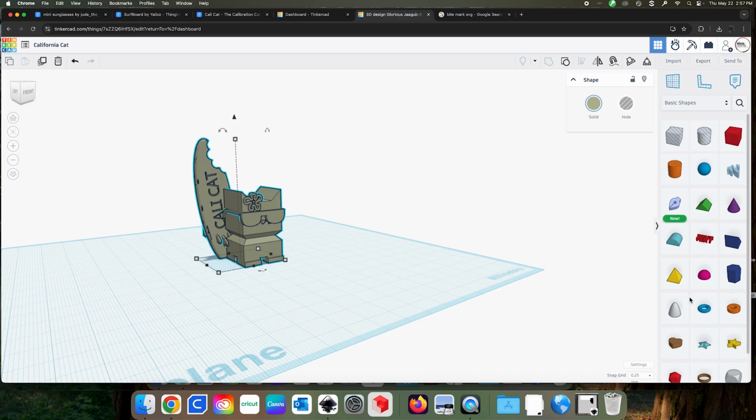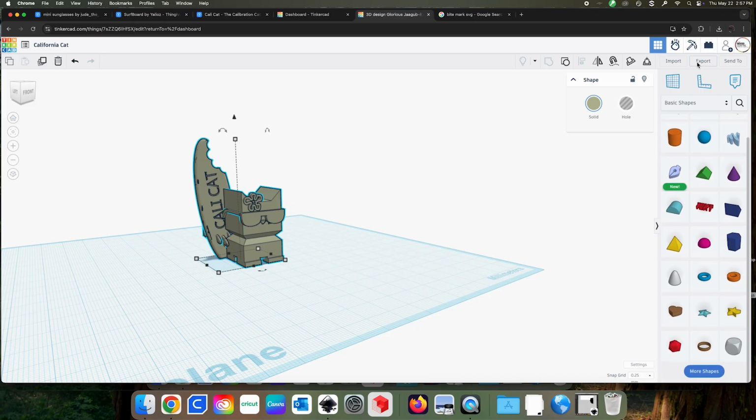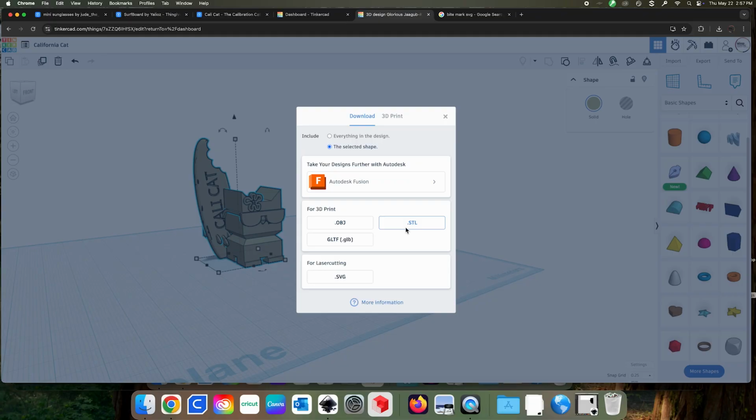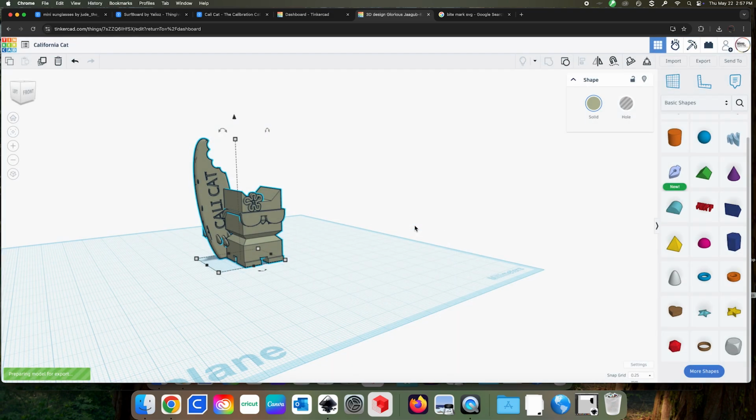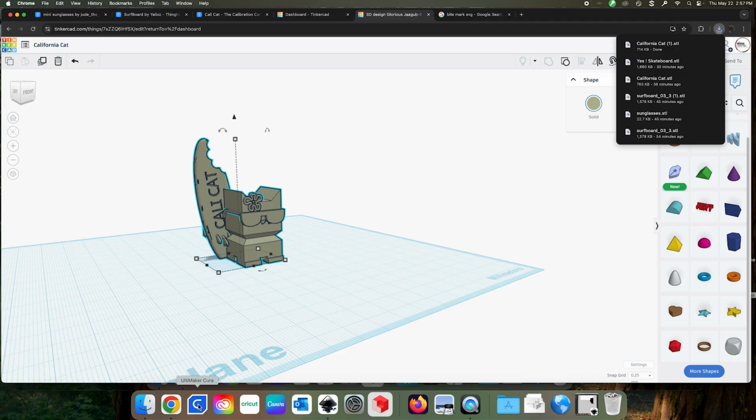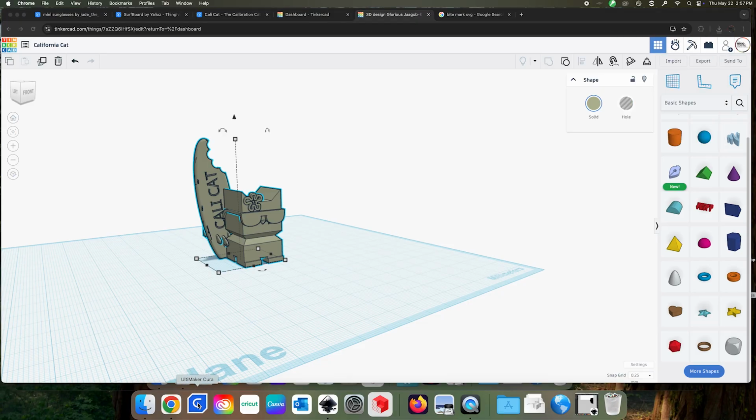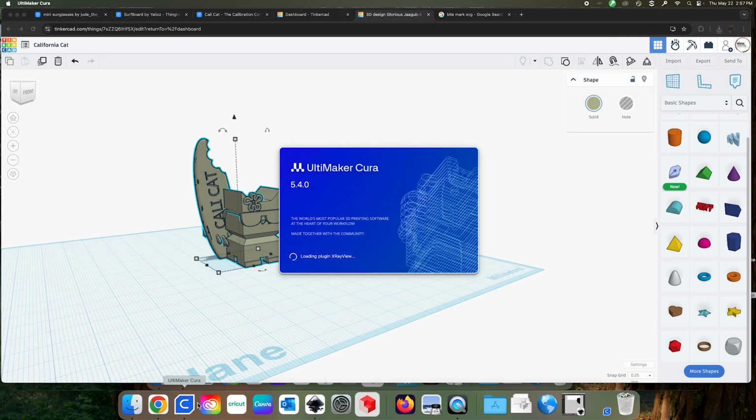Returning to the menu on the right, on the side of the import button we used earlier, we can find Export. And when we click on it, we can see that TinkerCAD will prompt us to select a file format to save it in. Most frequently, we're going to save it as a .stl, which is best for 3D printing. You may also have noticed that we can export our object back into a two-dimensional SVG file. If we choose this option, it will create a 2D vector based on the surface that is touching the print bed.